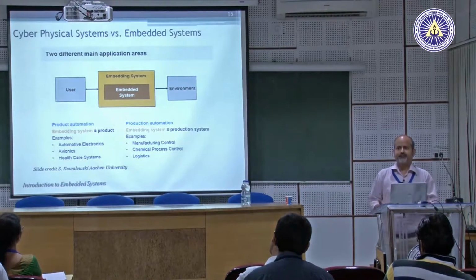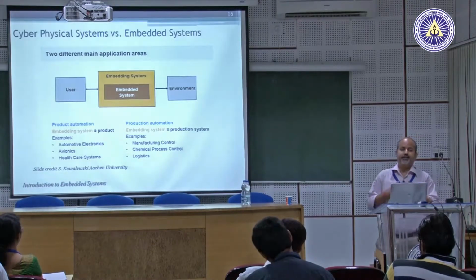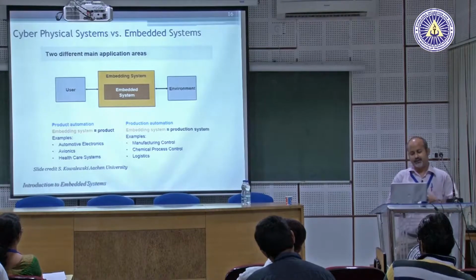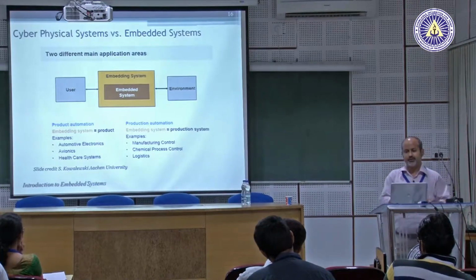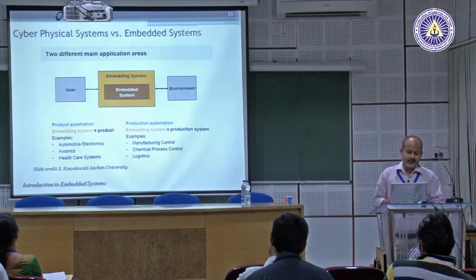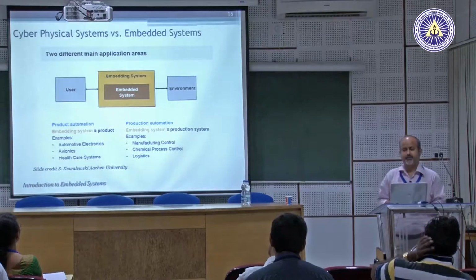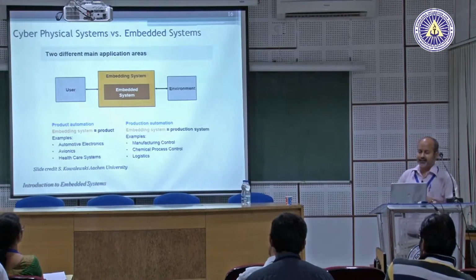The generator has to be under control so that it doesn't run away with weird speed and your generated power is no longer 50 hertz, and you will be in trouble, right? So there have to be sensors sending data to a controller. The controller sends actuation signals to decrease the speed at which the turbine is rotating, and things like that.